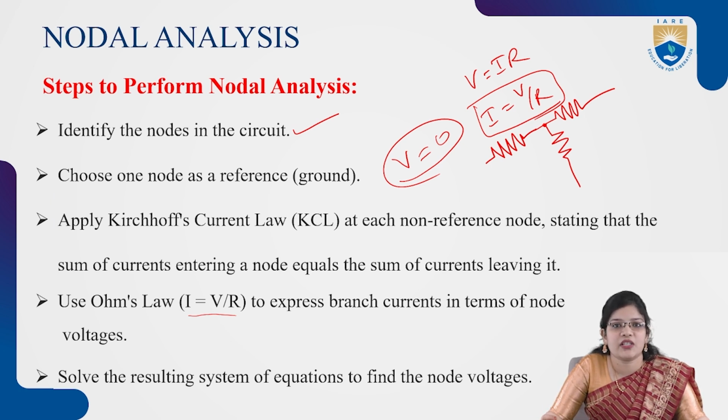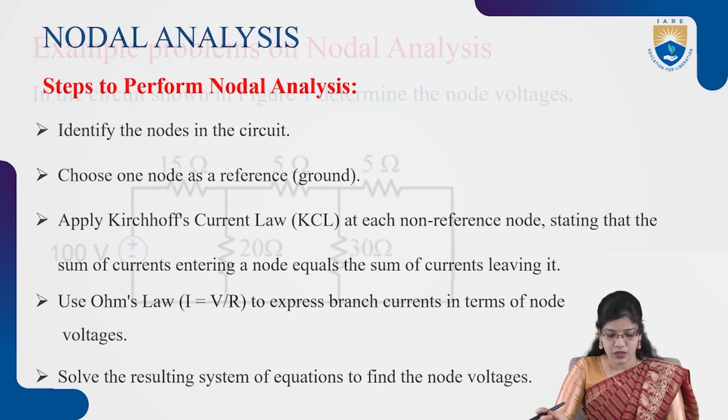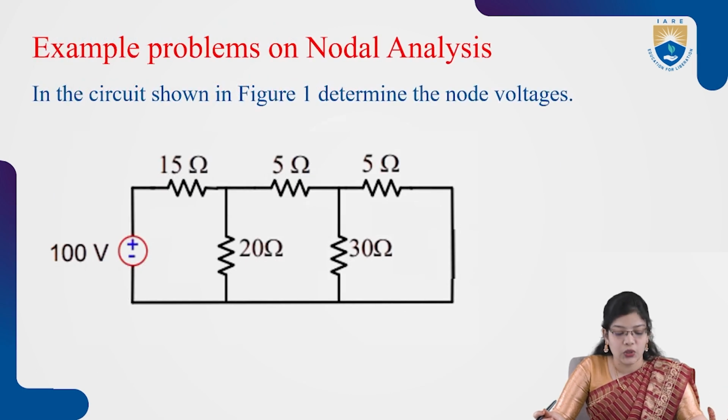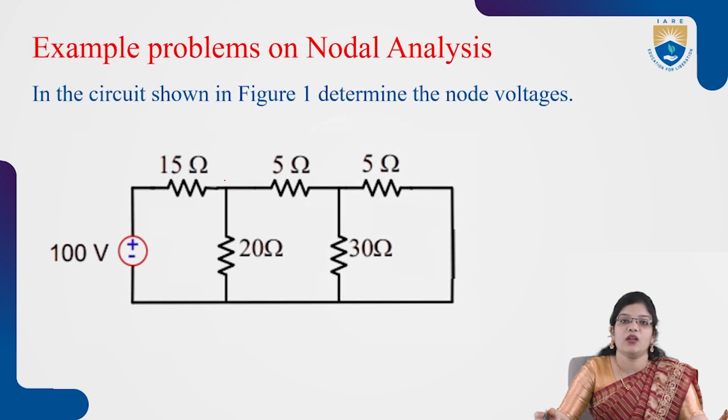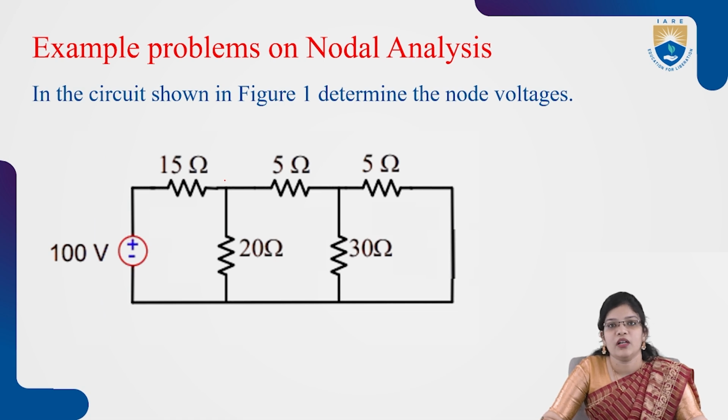In the previous lecture, we solved problems by considering only one node. In this lecture, we are going to consider two or three nodes and see how to calculate the node voltages by using two nodes. The first step of nodal analysis is to identify the node voltages.